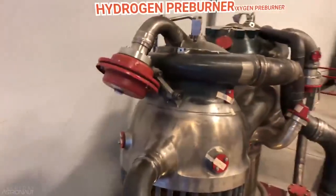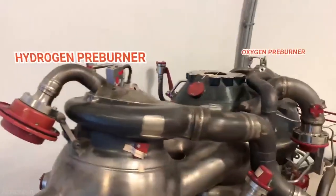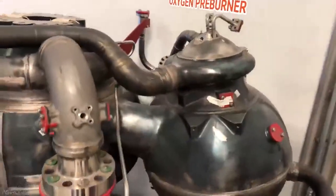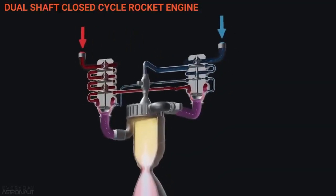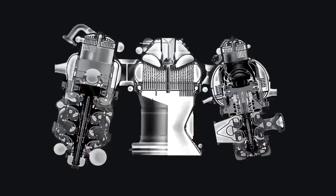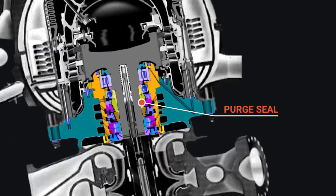Their design for the RS-25 called for dual preburners on two different shafts, both fuel-rich. One preburner would power the fuel pumps, and the other would power the oxygen pumps. But having high-pressure hot gaseous hydrogen in your preburner on the same shaft as high-pressure liquid oxygen is a recipe for disaster. If any of that hot gaseous fuel would make its way up the shaft and meet oxygen, it would be game over. So US engineers had to develop an extremely elaborate purge seal that prevented propellant traveling up or down the shaft by having even higher pressure inert helium in the middle of it.